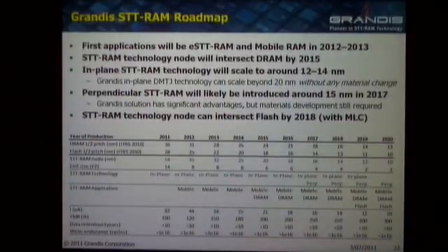Finally, this is the last slide. This is where I see the technology evolving. This is our roadmap compared with, as a reference, the DRAM and the flash roadmaps. Right here today, we're working at 54 nanometers, 14F squared with Hynix. The next design, we might actually skip down to a 30 nanometer design at 8F squared. And there I think these mobile applications become interesting.